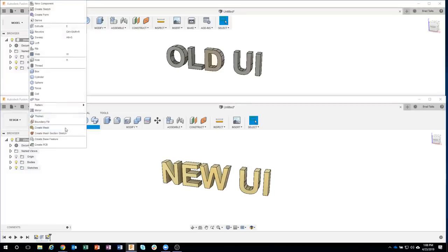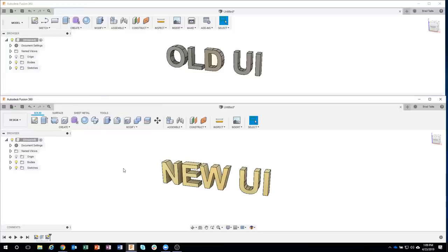The other one in there is, let's just do a cylinder. You'll see it says pin to shortcuts. Now I want to highlight what that means. So if I'm just out here in my screen, if I hit the S key on my keyboard, this brings up my shortcuts menu. And this is a very handy tool that I don't really show all that often, and I probably should show it more. But this S key, S is for shortcut, allows you to add the commands you use quite often.